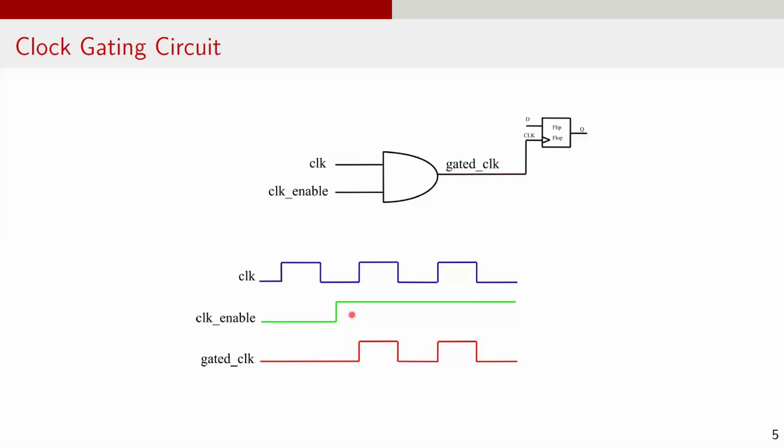To summarize, in order to optimize digital design efficiency, clock gating disables certain parts of the circuit that are idle or not in use. Consequently, the flip-flops in those sections do not switch states, avoiding unnecessary toggling and thereby reducing dynamic power consumption.